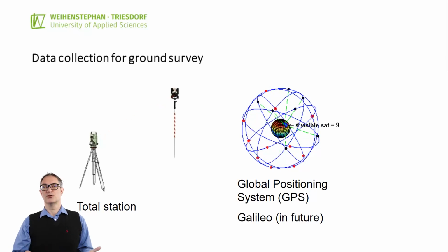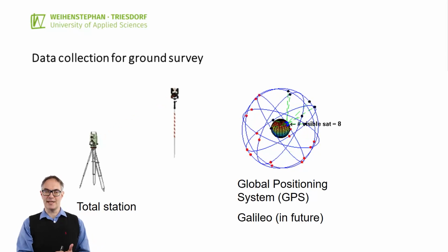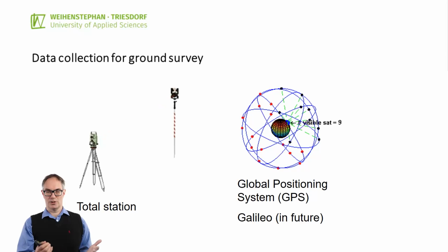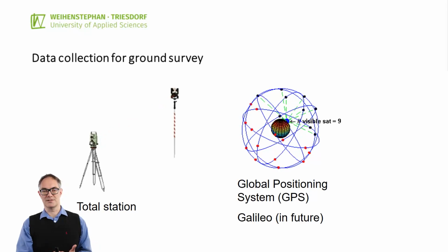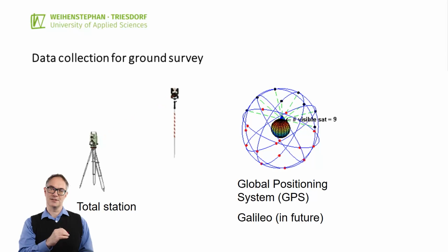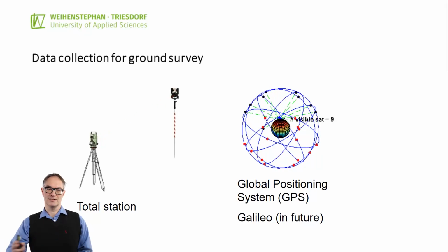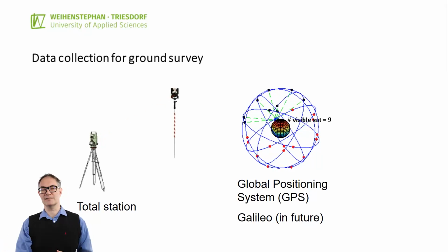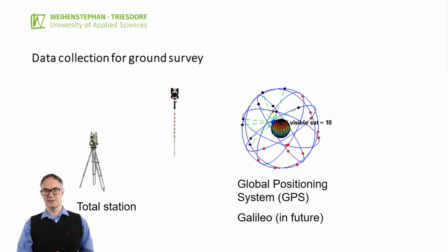We have to survey the terrain. And surveyors are usually using a total station put onto a point where we have the coordinates and the elevation, and then measuring through distance and angle to other points the elevation and location of that point. That's the classic conventional way.